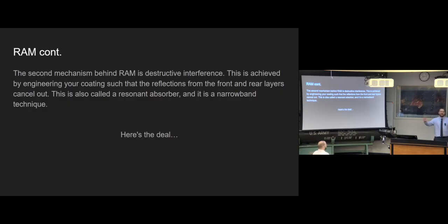And it's really strong, except it has a weakness. Absorption is wide band. It's not that frequency dependent. It can be used across a wide spectrum of frequencies. This one, it can't. If you want to make use of destructive interference, which is a very efficient way to minimize and prevent the radar returns from occurring, you have to pick a frequency and stick with it.